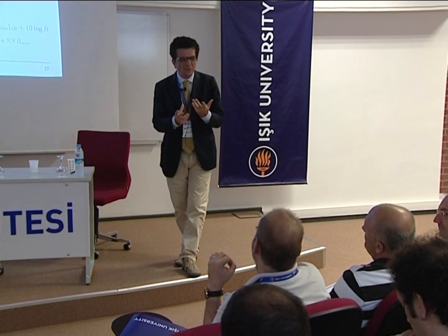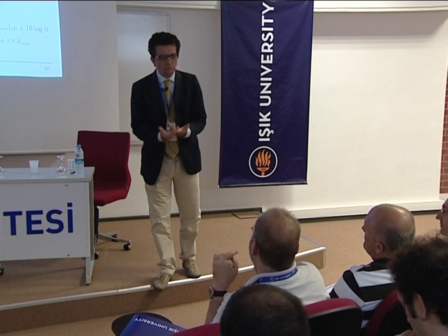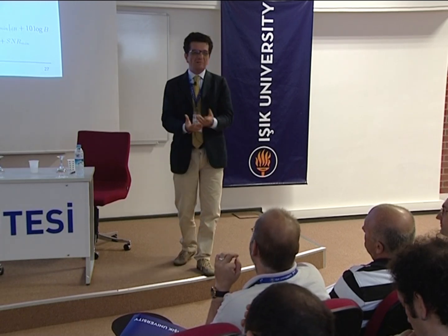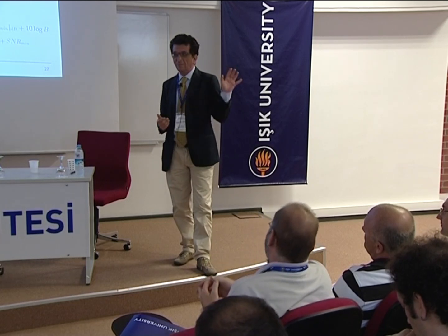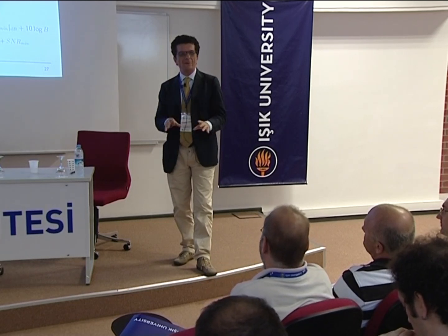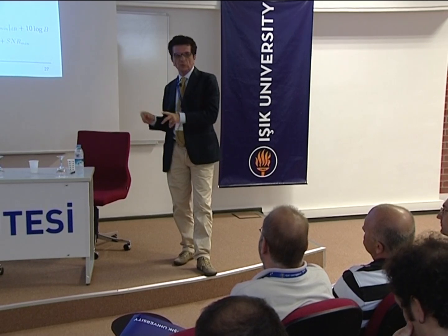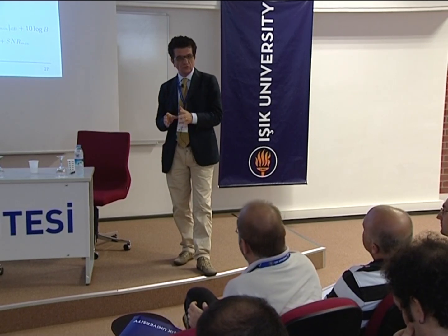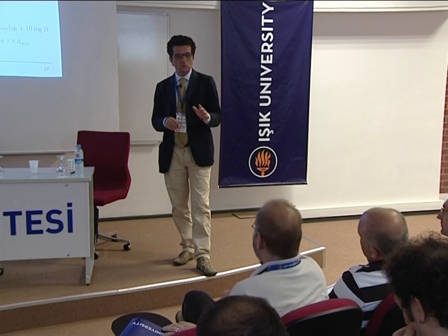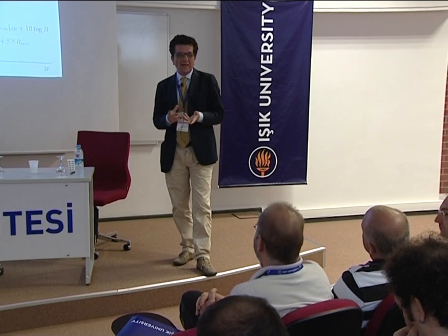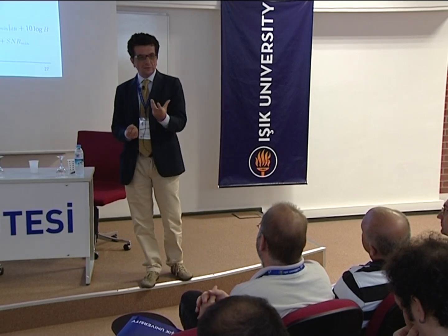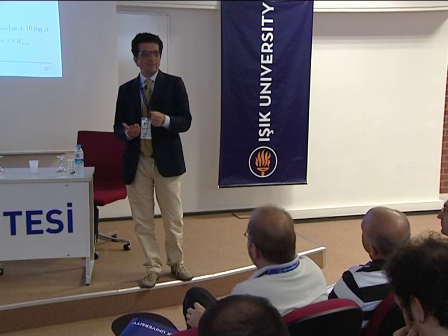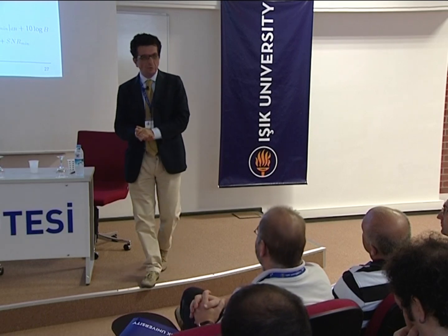You can improve something, but we tried, but not much. Well, a factor of 1.5, 1.3, but not much more. But that's, in my opinion, 60 gigahertz or where you have everything under control. At RF, where you use external off-chip components that are not under your control, you cannot. Because otherwise, for a company, its transceiver wouldn't be compatible with the others.